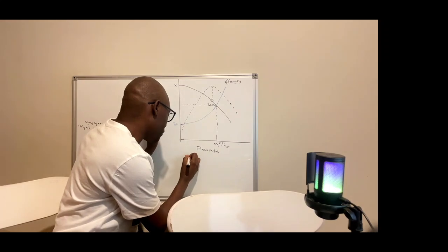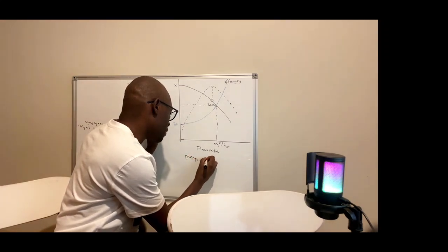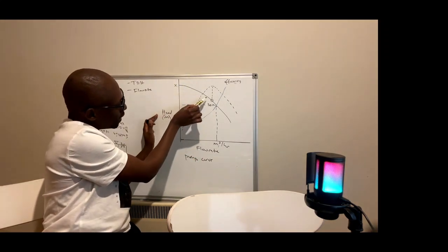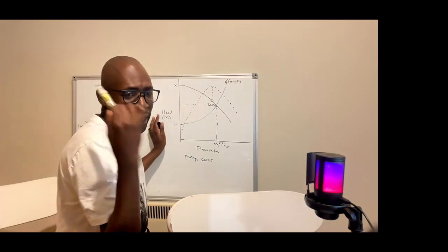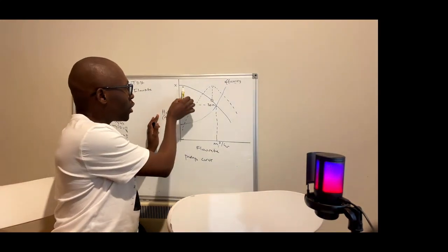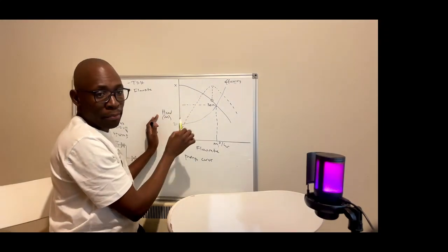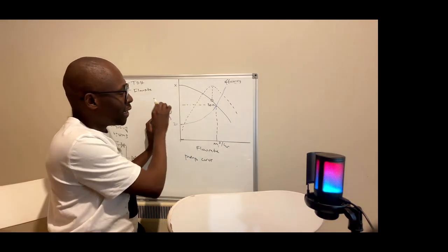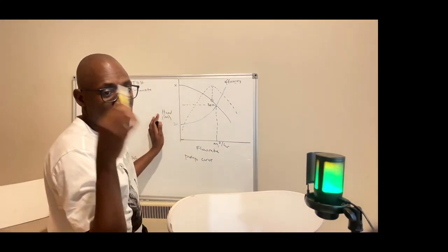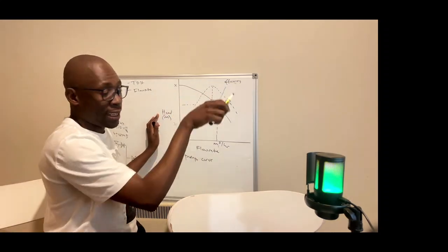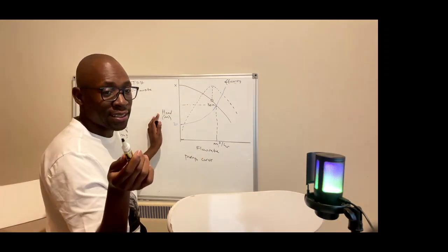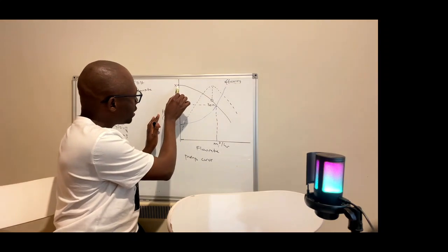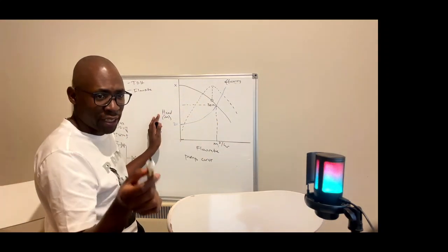The pump curve. In this case, our pump curve is this. This is a curve that is provided by the manufacturer. In some other pumps, you might see maybe 3 or 4 different pump curves. Those will be different sizes of impellers for the same pump, and each impeller will have its own profile of the pump curve. This line is showing the pump curve, provided by the manufacturer.